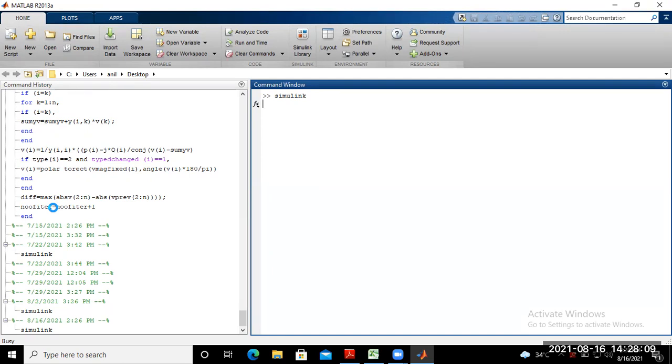It takes some more time. Wait for the new workspace. And first of all, you remember all the components that you require for simulation of the circuit, so that you can drag them from the Simulink library to the workspace.